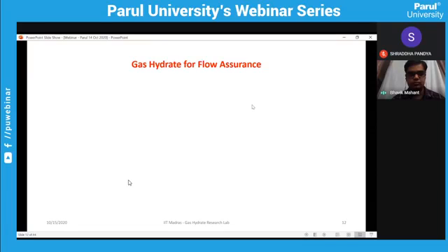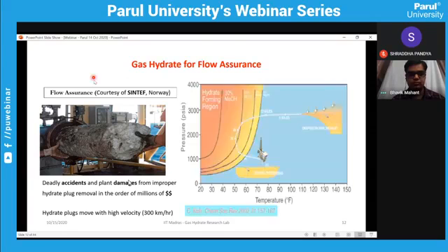So we have started with problems in the gas hydrate industry, how we come to know, and what research is going on in the different types of sectors. Basically this is for flow assurance. As we know, everyone is using natural gas, maybe in Vadodara also. Everyone has a gas pipeline in their kitchen. It comes from Alaska, majorly Alaska and Qatar, by shipping, and after it reaches the Dahej terminal, it comes to our house through piping. In foreign countries the temperature is very low, so there might be chances it can convert into solid and plug the pipeline.